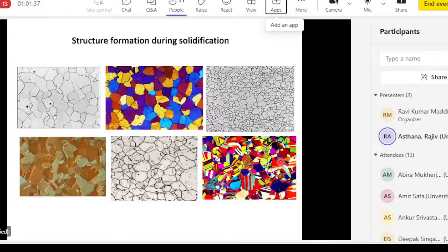We also know that a fine grain size gives higher strength at room temperature as compared to a coarse one. For example, pour aluminum in a sand mold versus aluminum in a copper mold. The aluminum casting in the copper mold will be stronger because of the finer grain structure. But again, you cannot change your production line from sand casting to permanent mold casting. So there are ways to get fine grains even in sand castings, by inoculation methods.